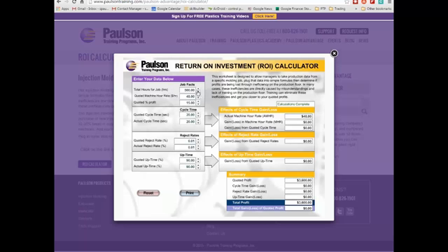So let's just say, and these are assumptions, and I'm going to mention percentages more than absolute values so we can all relate. But it's a 500-hour job, 500 hours of machine time. Quoted machine hour rate's 48, could be anything. Quoted profits 15%, fairly typical. Quoted cycle time 20 seconds, and here's where we get into the ability to manipulate what happens in the real world and see what happens to our quoted profits. So you can see down in the lower right, we're scheduled to make $3,600 on this job. You could expand these factors by 10, by 100, doesn't matter. The values, percentage-wise and from a business perspective, remain the same.